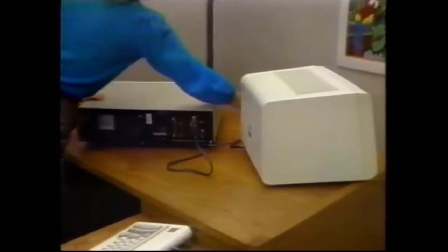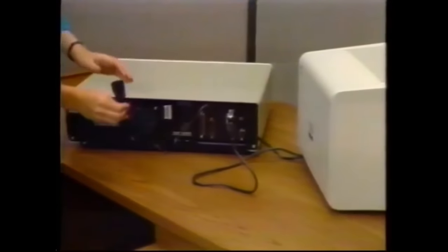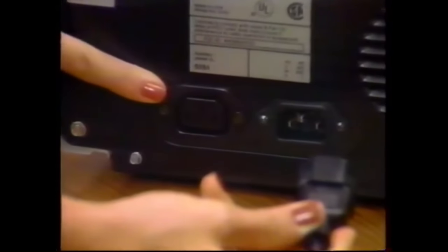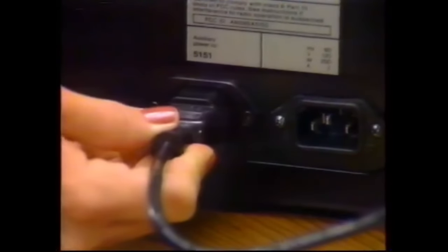Again, be sure you don't have the main power cable to your computer itself plugged into any electrical power. Your IBM monochrome display will get its AC power from the connector on the back of your computer. Plug the electrical power connector from the IBM monitor into the auxiliary power connector on the far left of the back panel of your computer.